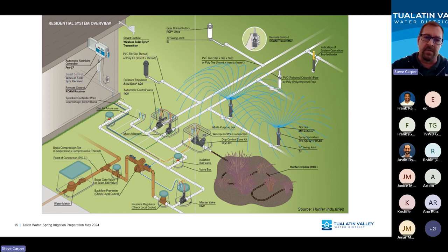Just downstream of that, you'll find your backflow device. In this image, it's above ground, as Cal said. There's various types. Most common in our area, again, is going to be a double check assembly, which will be subgrade in a valve box, generally a rectangular box with a green lid about the size of a 9x13 baking pan, if you will.